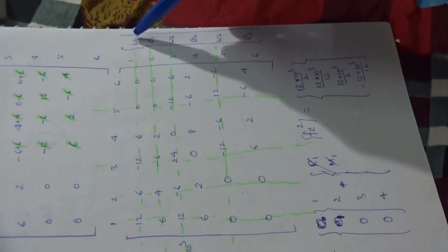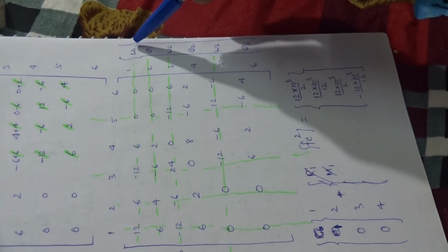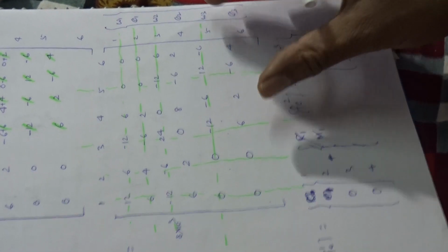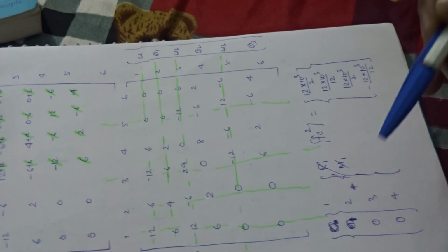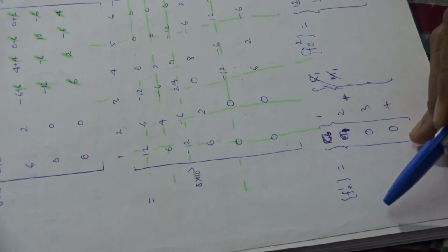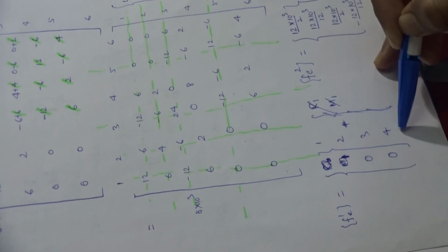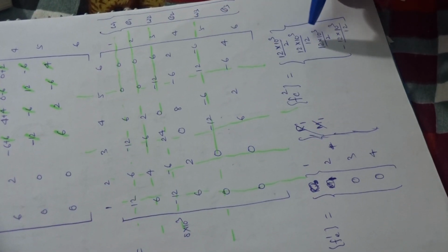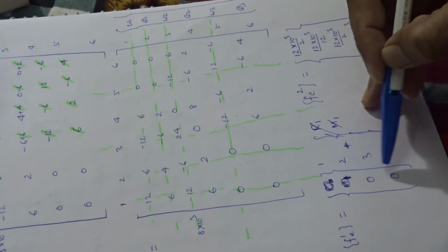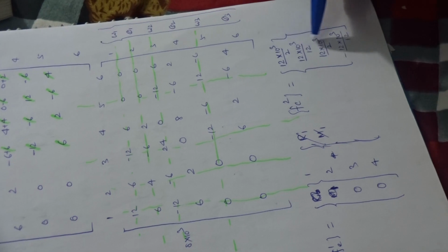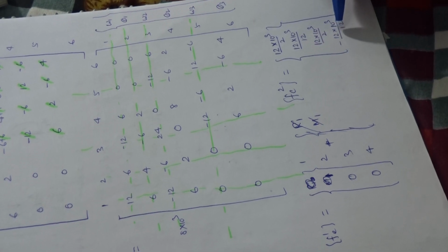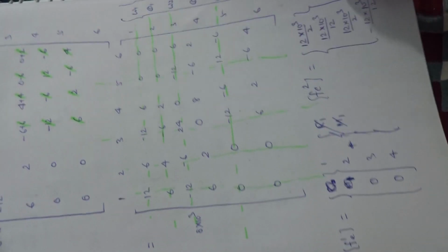And we multiply this matrix by w1, theta 1, w2, theta 2, w3, theta 3, and this multiplied by this is equal to the force matrix. So separately I evaluated the force matrix. FE1 is 1, 2, 3, 4, and FE2 is the distributed load. Here there is no distributed load, so 0 0 0 0 for element 1. For element 2, we use the previous formula for the distributed load and evaluated the force matrix for element 2.